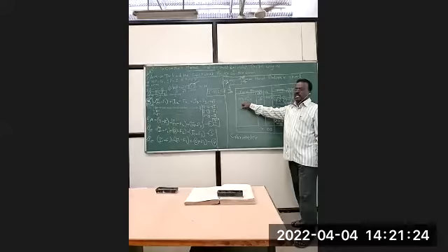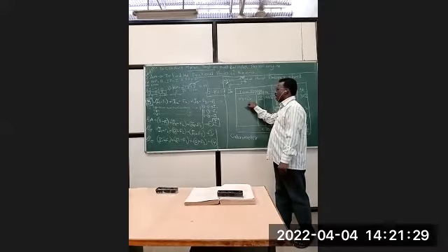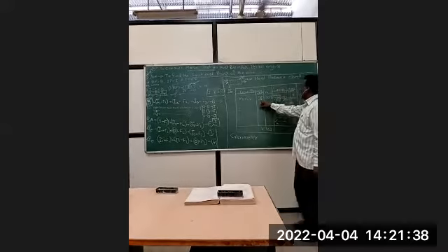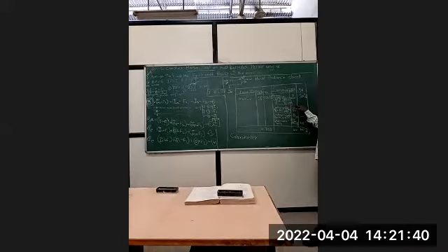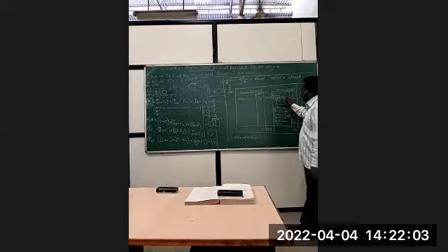By calculating the amount of fuel consumed by the engine and multiplying it by the calorific value of the fuel, we can find out the amount of energy in the fuel which we have supplied to the engine. And then coming to this side, some part of that energy is being converted into work. How to find out? We have BP is equal to 2 pi NT by 60. This much kilowatts of energy is being converted into work. So some amount X is being converted into power, which was Y kilowatt, that we have found out by using this formula.